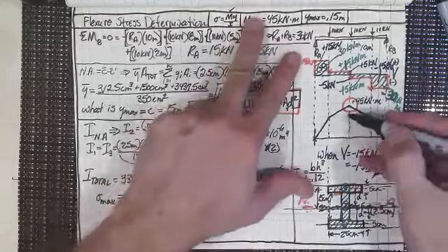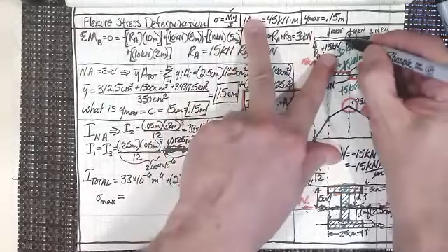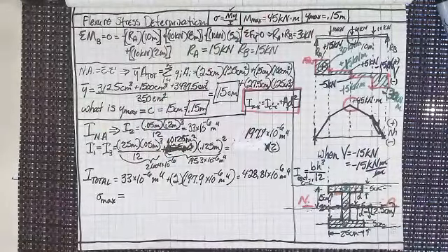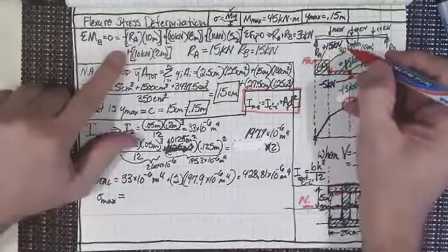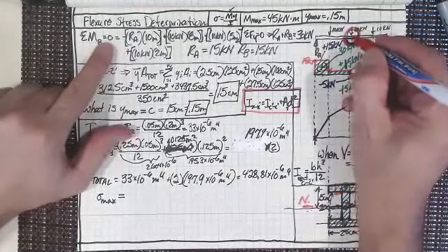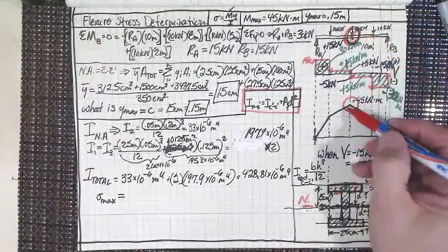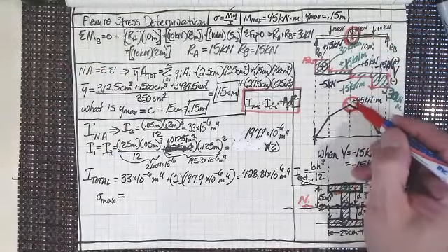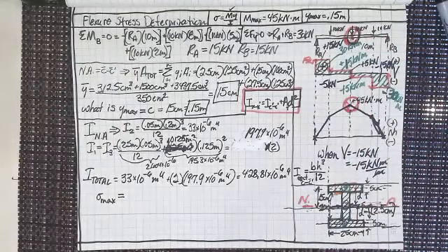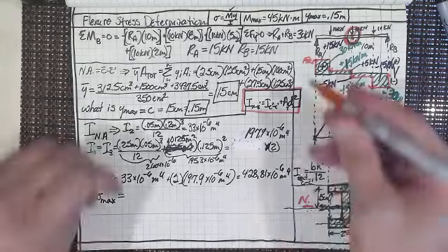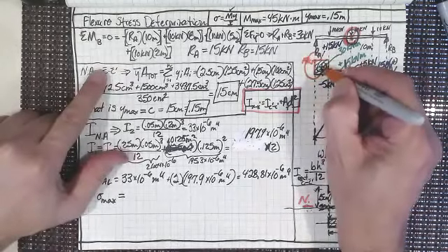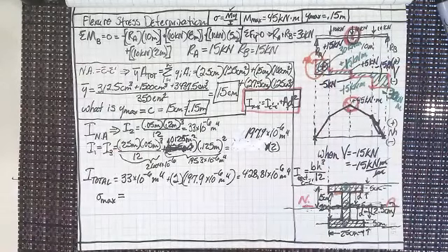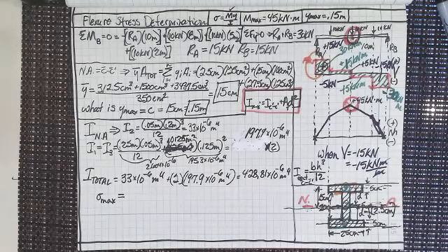Where's this going to occur? It's going to occur right there, isn't it? I shouldn't have used that color. I should have used this color. It's going to occur right there. That's where the break is going to occur, because that's where our maximum bending moment is, right? Shear breaks occur where the maximum shear stress is. But there's almost no shear breaks that you have to worry about, and you can't learn everything in this class,